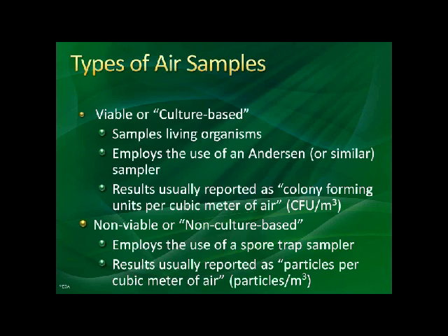In a simple base, or your preliminaries, you do non-viable. This uses a spore trap. Very simple. You set it up for a certain amount of time, a certain amount of liters, and then the lab will report it to you in whatever the particles are per cubic meter of airspace. There's a long calculation they do, but they'll report it to you. What I always suggest as a start for those who are already doing or thinking about getting into viable is to do a non-viable test first to find out what is there in the air, to then derive what you're going to do for viables.